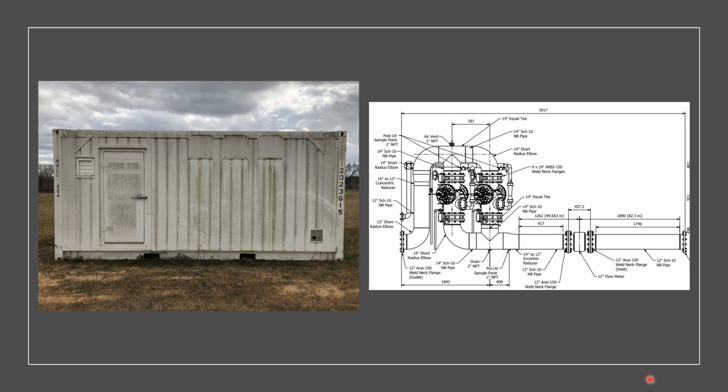Each containerized unit has 2 UV reactors arranged in parallel. The piping is 12-inch diameter, and if you look at the picture to the right, you can see the inlet side on the very right side of that picture. Water flows along the pipe to the left and enters the bottom of both reactors. Each reactor has isolation valves, so you can run one and leave the other one shut down, or you can run both. Water floods the reactors up from the bottom and overflows out the top. The flow then recombines and exits the container to the left of that picture.